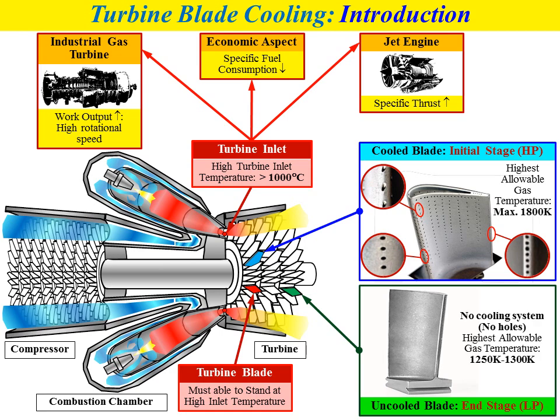For this type of blade, no cooling system is provided, so there are no holes on the surface of the blade. The highest allowable gas temperature for this kind of blade is between 1250 Kelvin and 1300 Kelvin.